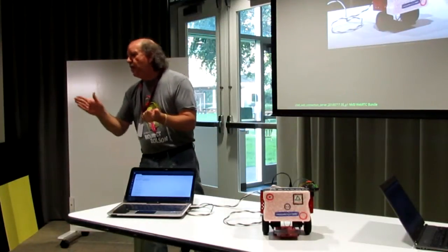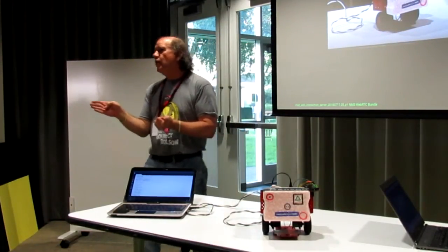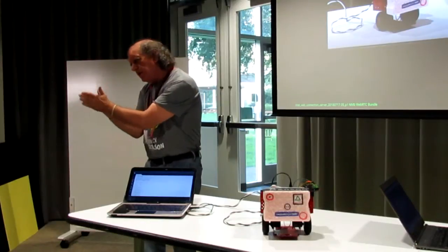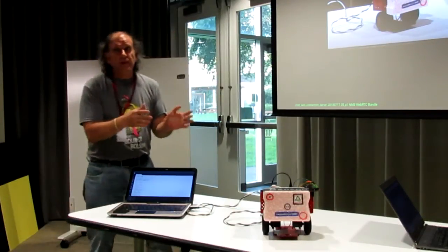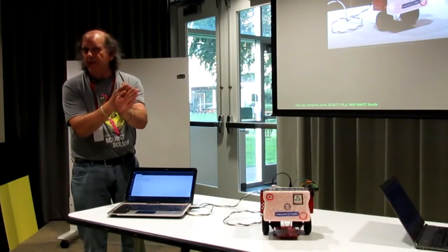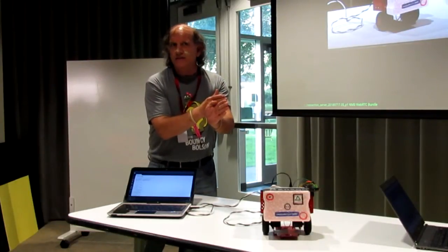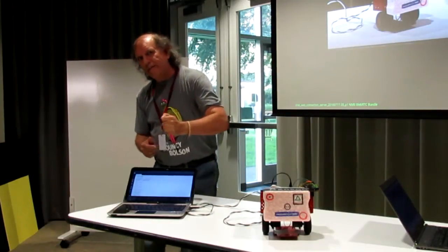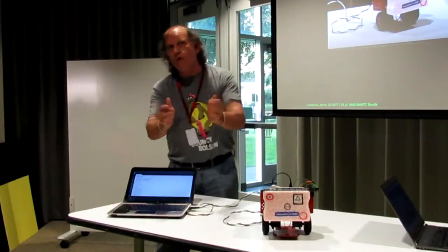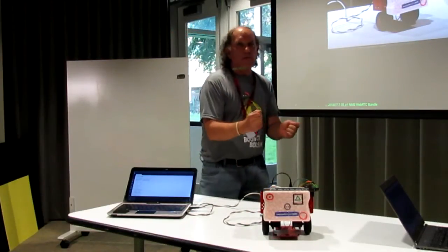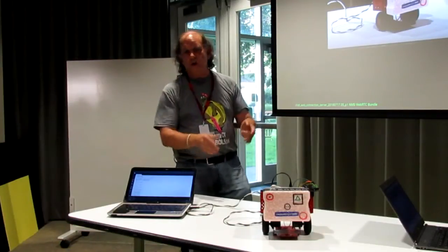And so now the robot knows that it needs to stay in this 45-degree corridor. If I'm tracking north, 315 and 45, if the bearing that I'm traveling is lower than 315 and greater than 180, I need to actuate my left wheel to get back into that 45-degree corridor. If my bearing is greater than 45 and less than 180, I'll actuate my right wheel. So the point being, I know what direction I need to go in, and I can send the robot in that direction.